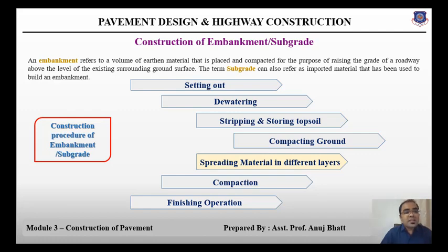The embankment material shall be spread in layers not exceeding 250 mm compacted thickness when using vibratory roller, over the entire area with the dozer, and finished by a motor grader. When the existing embankment is to be widened, continuous horizontal benches shall be cut into the old slope to ensure adequate bond.